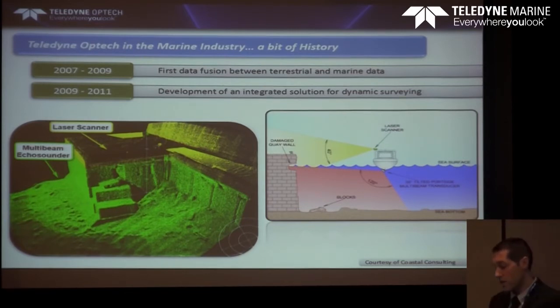What is surprising is that usually with the laser scanner you get a million points very quickly, but if you check the bathymetry, the resolution you get is also really impressive. When you have everything combined together, I've colored it with two different colors now, but usually you can also use the intensity, and everything looks like one single point cloud.